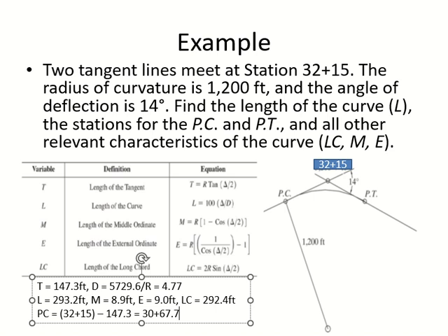So for the sake of construction, we rely on the first approach, which is adding the length. Because my objective is the curve. Tangent is not my problem. If you add tangent and you don't get to the end of the curve, this is a problem. But if you go from PC and you add the length, you get to the end of the curve. So whatever difference we have, we don't want to put it in the curve. In the end, you want to fit the curve between PC and PT, even if it is not accurate from the PI. PI is not my problem. My problem is start of the curve and end.